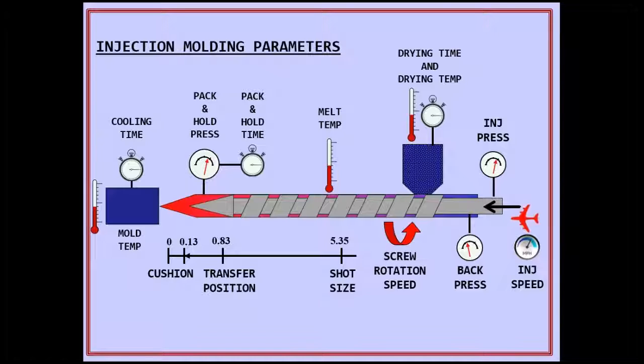Okay, for cosmetic reasons, you might need to play with injection speeds, right? You can do a viscosity curve, but I'll tell you the viscosity curve is the last thing that I typically do, or on my list. I do it first, of course, as per this thing, but it's the one that I look at last. Inject as fast as you need, not what the viscosity curve tells you, or as fast as you can. Because there's multiple things. Again, on my website, I've written 11 reasons why not to do a viscosity curve, or not to use the data from a viscosity curve. So you might want to play with that, but that's it.